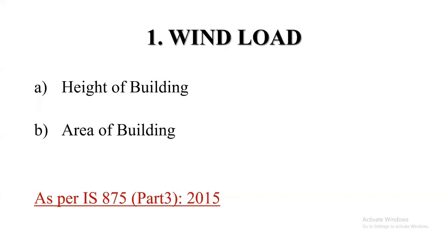So they use wind load, and they also sometimes add snow load because sometimes it snows very rarely. But seismic in this zone, in this country, there's not much of earthquake. It's not earthquake prone basically. So I don't think so. They consider seismic, but yeah. Okay. So they are different.